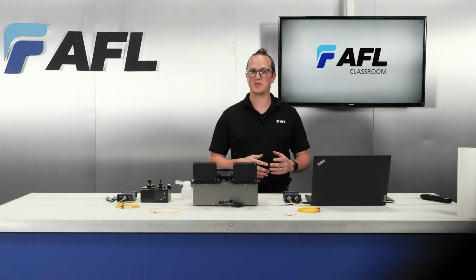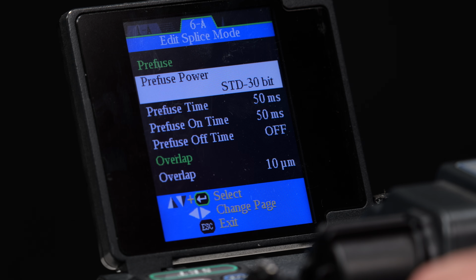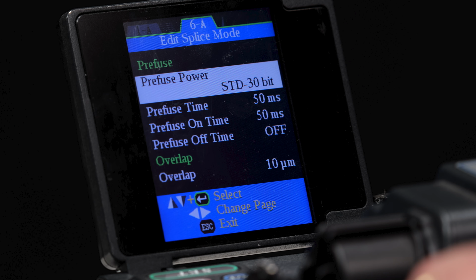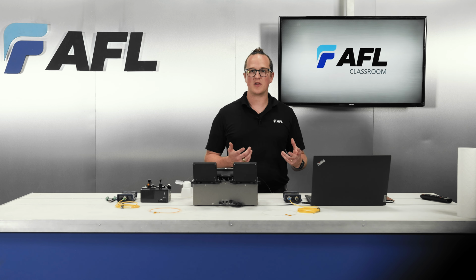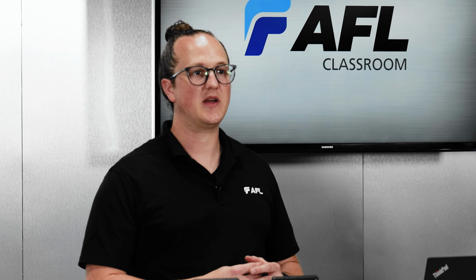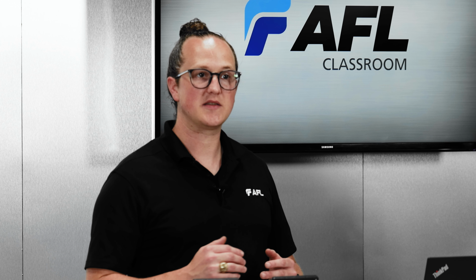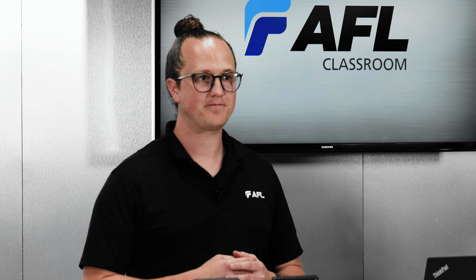I'll start by selecting my arc calibration method and performing the arc calibration. For the single mode fibers I have here, I'll be using the standard arc calibration. Next, I'll optimize fusion time and power, followed by the prefusion time and prefusion power. If necessary, after this point, I can optimize the gap, overlap, electrode gap, and other splicing related settings as I move down the list. During the process, I've made sure to record data from each splice. This will serve as the data set for optimizing the loss estimation.